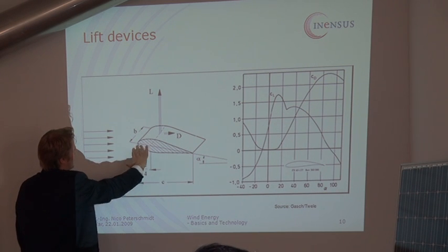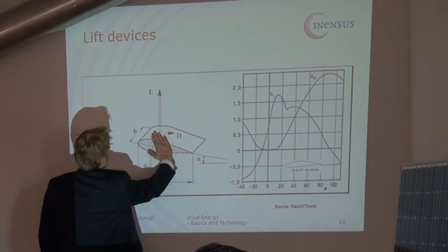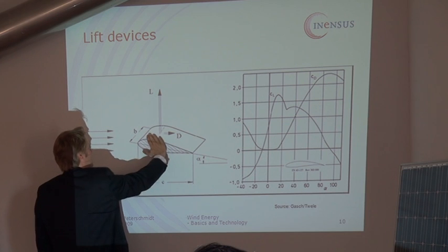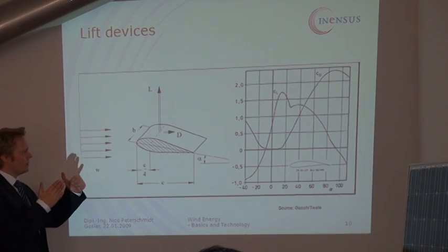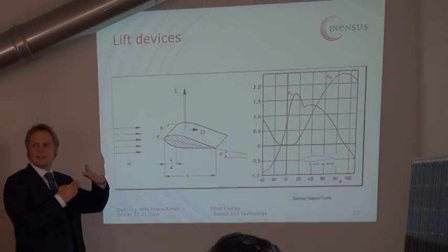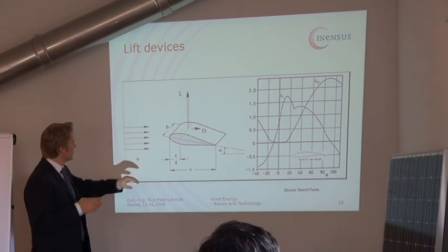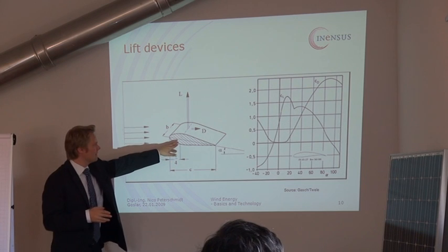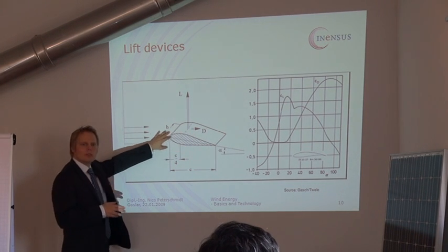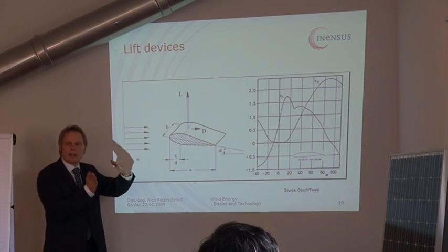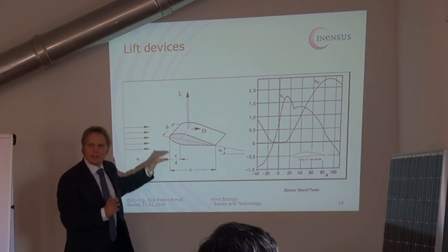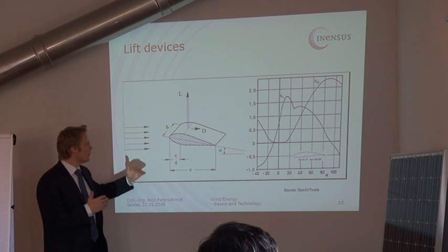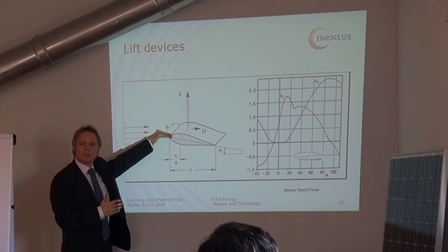And then you've got different angles which you like to adjust the blade according to the wind's movement. Now if you add up the vectors of the wind speed and the movement of the rotor blades, you get a resulting vector. It has got a speed and an angle of attack towards the blade.